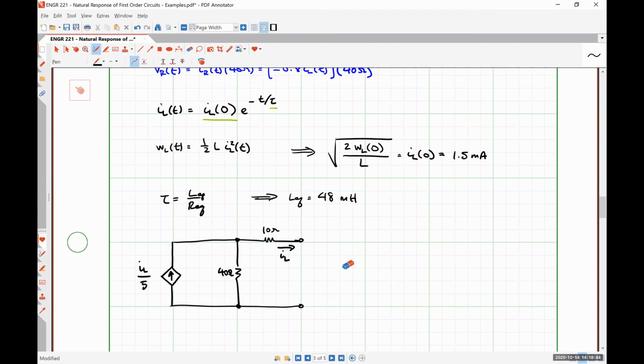So let me explain why it's not voltage. Okay. If I apply a current source, let's say direction down of 1 amp, what have I just done? I've set I_L to have a specific value so that my dependent source no longer behaves like a dependent source, right?